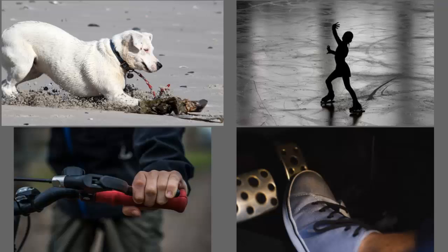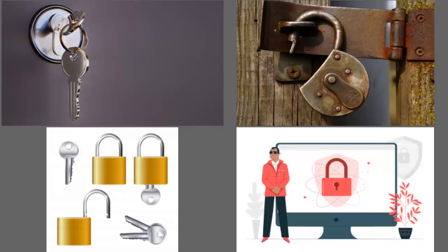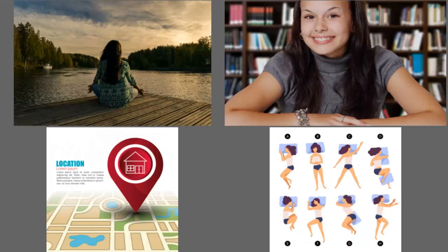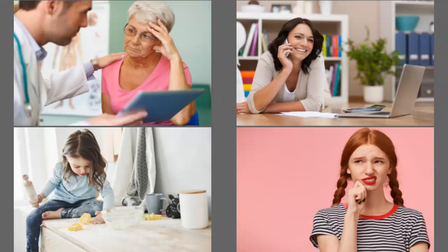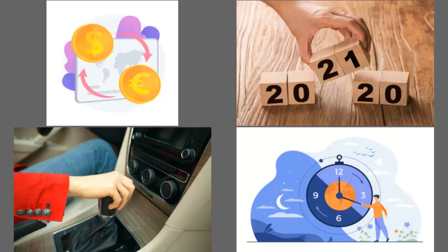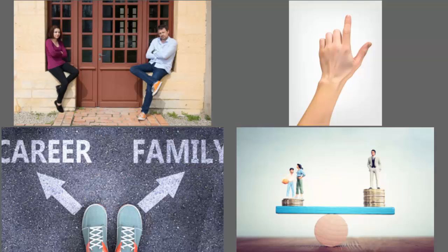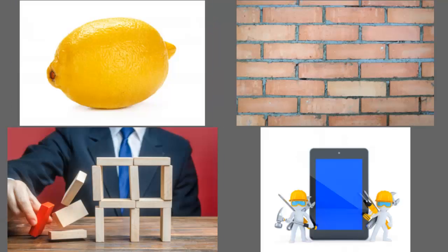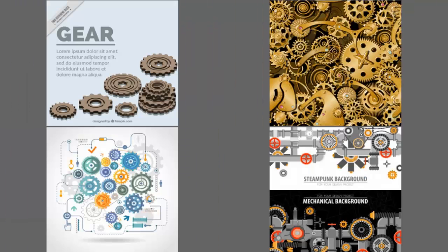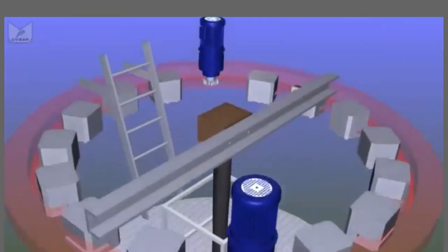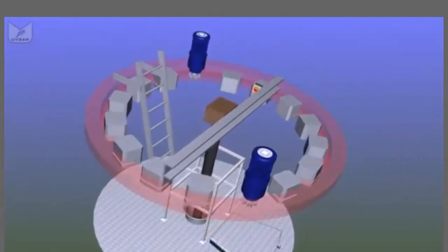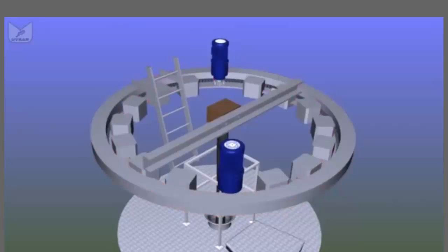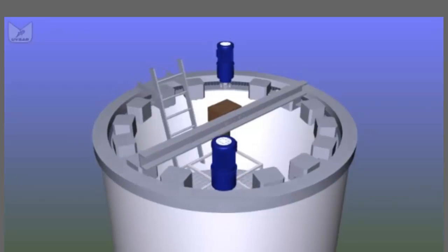A series of disc brakes run around that yaw ring to lock it in position when the wind isn't changing direction, and when it is, we have a series of either electric or hydraulic motors that rotate the entire mechanism around on the top of the tower.